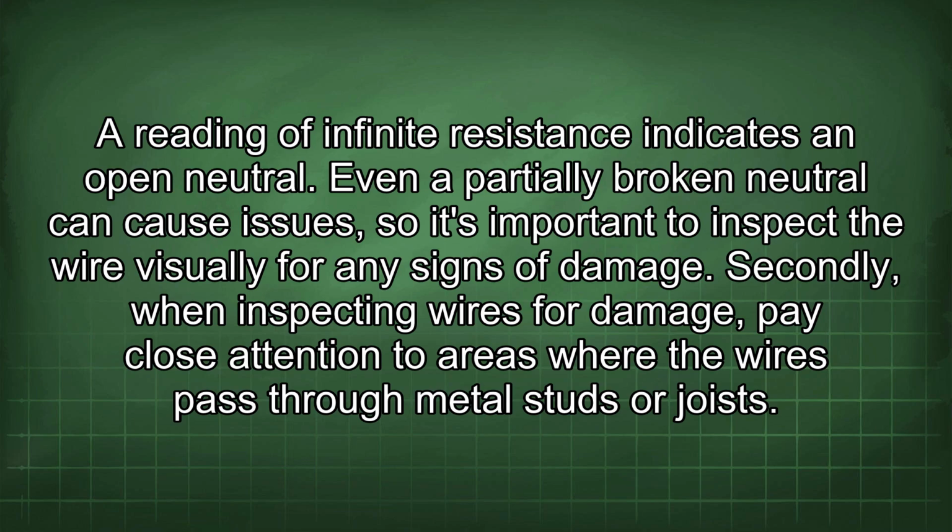Even a partially broken neutral can cause issues, so it's important to inspect the wire visually for any signs of damage. Secondly, when inspecting wires for damage, pay close attention to areas where the wires pass through metal studs or joists.